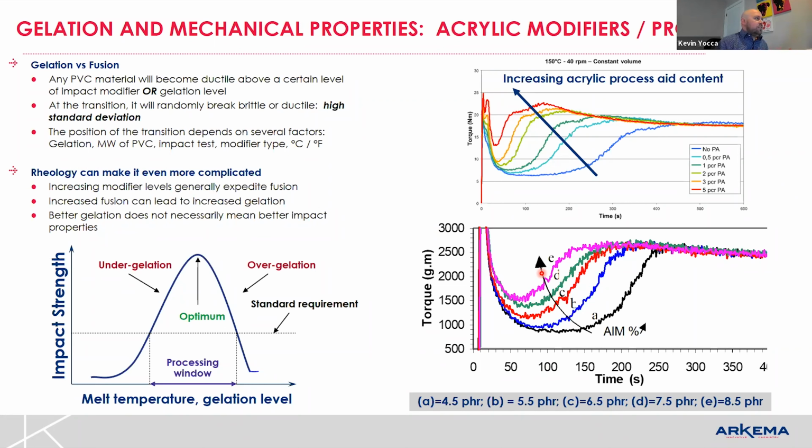So all of these different levers, when they come together, are things that you have to think about when you're trying to modify a formulation. One of the most common that I've seen over the years, obviously since the 90s going into the 2000s, was the idea of low rubber versus high rubber impact modifiers. So what would that help us do? It would help us reach our optimum mechanical properties and impact strength. But now with less shell content, we were changing the rheology of the overall formulation itself.